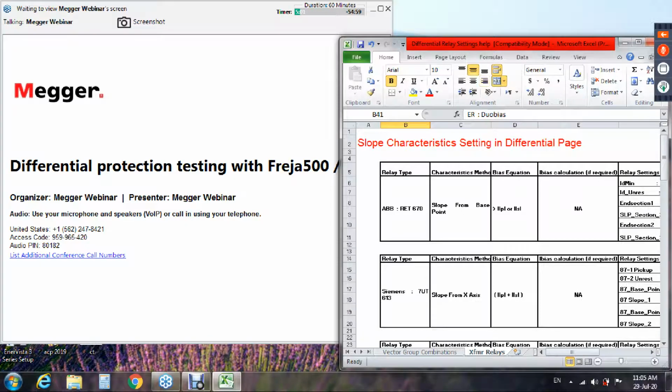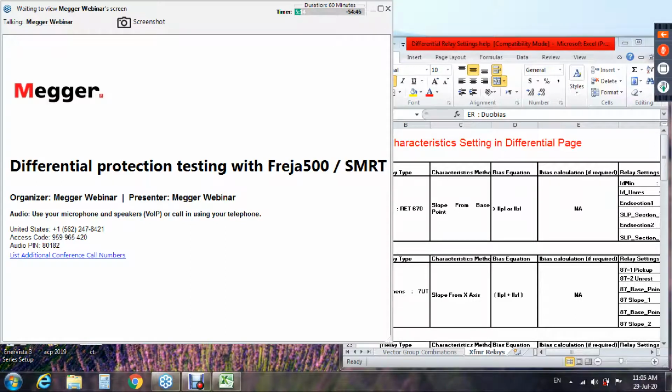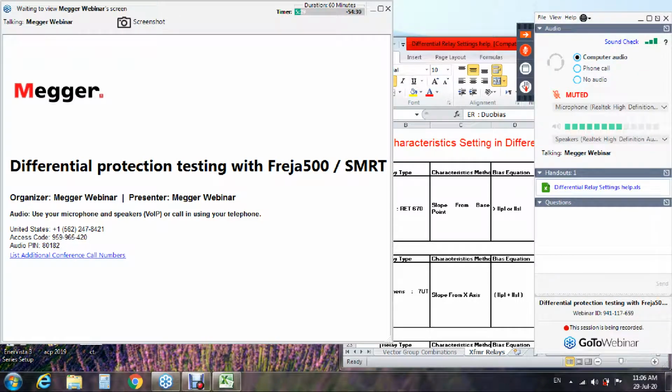Thus, if there is a path for the current outside of these measuring zones, usually stated by current transformers, CTs, if there is a leakage to the ground or between two phases or whatever, the differential current will not be equal to 0. Thus, the current is flowing into a place or direction that is not normal for it, meaning you have basically a fault, and then a trip will occur. This principle of protection gives you 100% selectivity on your protected area, and thus allows you to give a very fast operation in case of a fault. Usually this operation is instantaneous, 0 milliseconds.